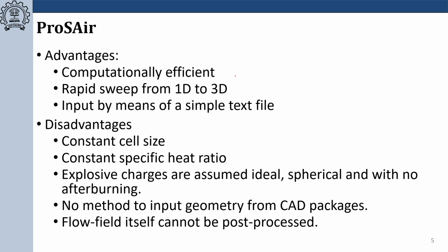So what are the advantages? It is computationally very fast compared to state-of-the-art software such as LS-DYNA and AUTODYN. It will take much less time to solve the problem. Another advantage is the rapid sweep from one dimensional to three dimensional. As we previously discussed, it first solves the problem in one dimension, then it can remap into two dimensional and three dimensional, but it has its own limitations that we will discuss later on. And input is by means of a simple text file. Either you can use the graphical user interface or the simple text file to give input to the software.